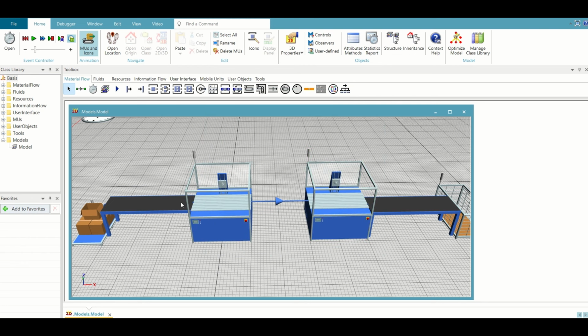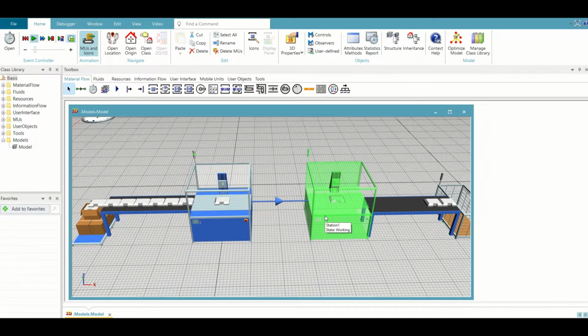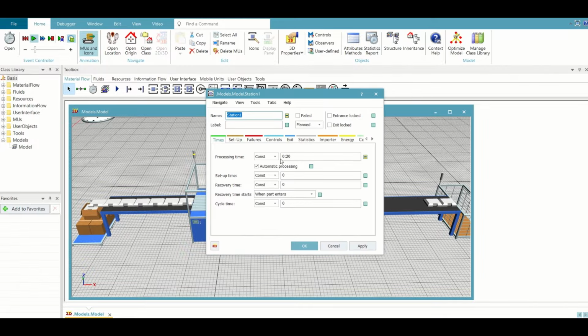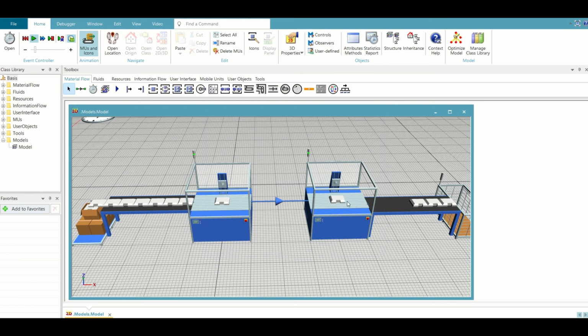Because of that, you are going to see a blockage in the station and idleness in this station. Okay, so this is going to be a fully utilized station. You can see the conveyor with minimum parts and more parts onto the conveyor, because this station has the least cycle time, that is, this station is fastest, and this station we have intentionally made to work slower, and this is going to act as the showstopper for us.